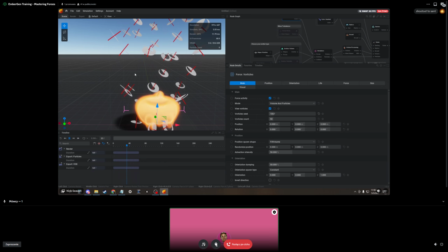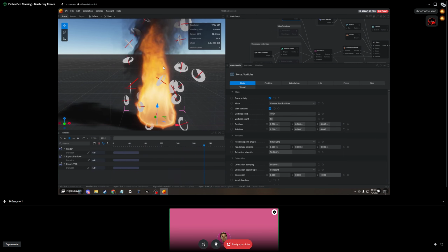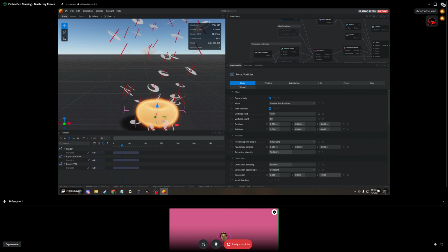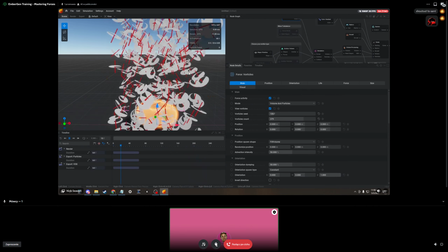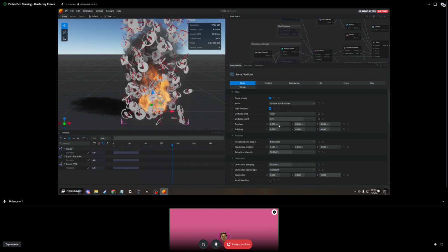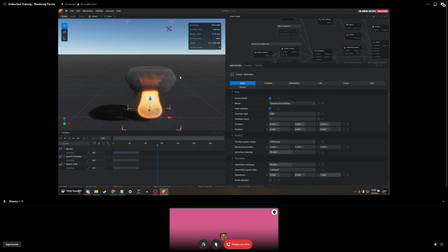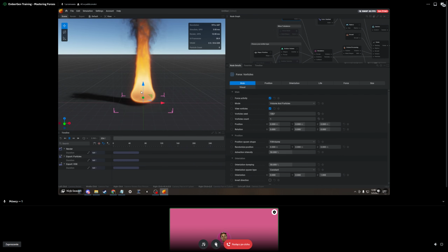As the gist, you have a seed, so you can spawn vorticles in different locations, and it's a good way to localize things and randomize your simulation. You can also increase your vorticles count. If you want more chaos, you can have more vorticles. You can even have just one vorticle at a time if you want, and it'll do its thing and affect the simulation wherever it spawns. We can say have our little default of 50.